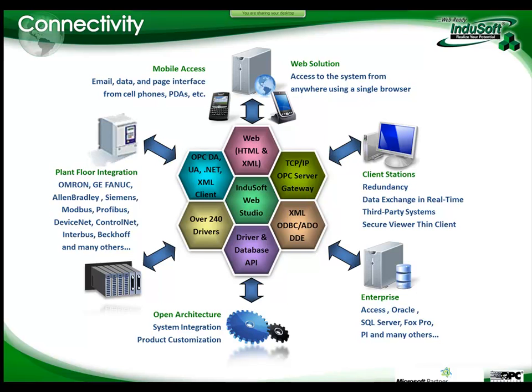Let's say that you're writing your own program using Visual Studio, using C++, C#, Visual Basic, and you need to have access to the InduSoft information. We do offer the tools to do that, so you can get the driver toolkit and write your own driver, or if you're writing your own application, you can access through a DLL or ActiveX our tag values, our tag fields, all this type of thing.